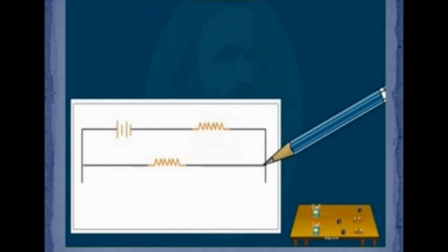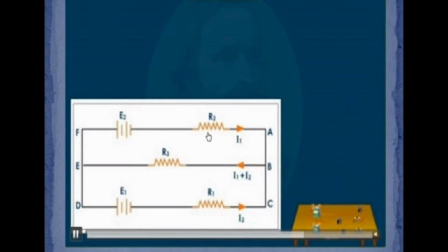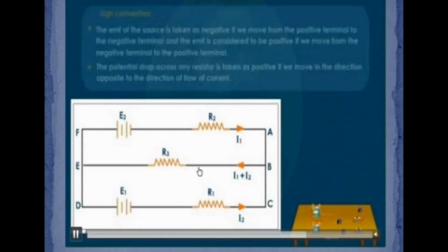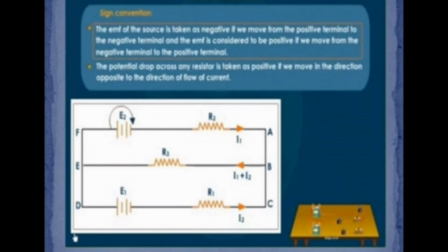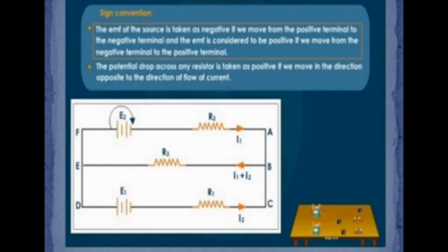That is Kirchhoff's first rule. Second rule: we can take the closed surface. Closed surface means the closed loop. A battery and resistances are connected in a closed loop. That law states that the product of current and resistance in each part of any closed circuit is equal to the EMF of the closed circuit.